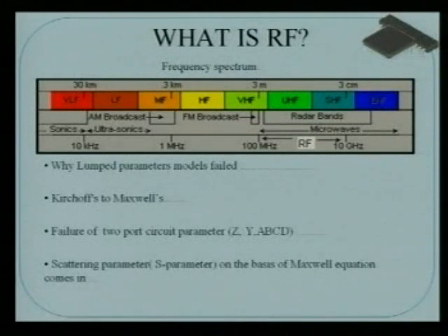That is, we will use the same digital CMOS process which can be used for digital circuit design, and it can also be used for fabricating an RFIC. What is the advantage of that? You can have a large amount of digital processing along with your RF front end. Together you can have a single chip solution or SoC. Therefore, the challenge today is to implement low power RF circuits using the standard digital CMOS process without going into exotic processes, to make the cost less and less.